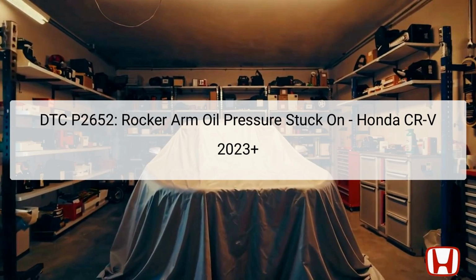The diagnostic trouble code DTC P2652 indicates that there is an abnormality with the rocker arm oil pressure in a Honda CR-V model from 2023 and onward. The code signifies that the output from the rocker arm oil pressure sensor remains excessively high when the rocker arm oil control solenoid is in an off state.